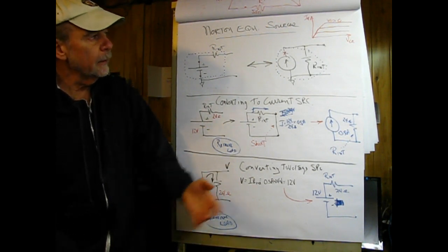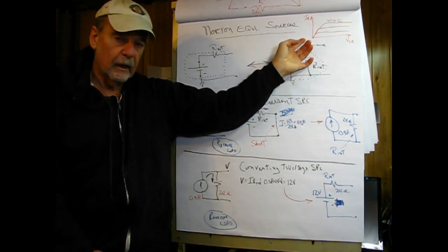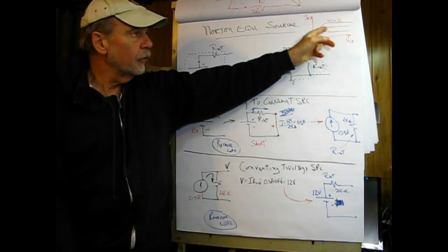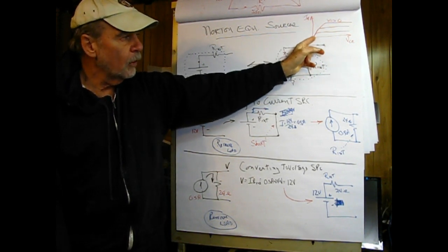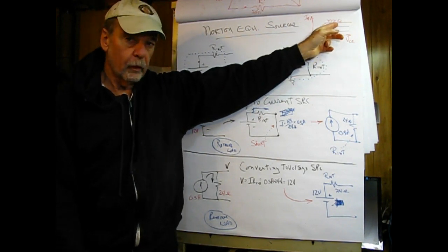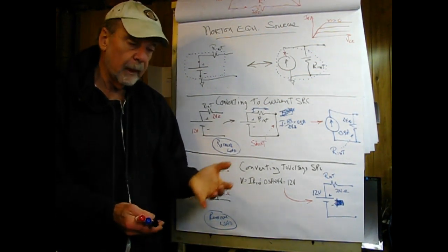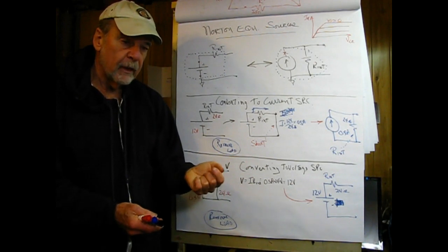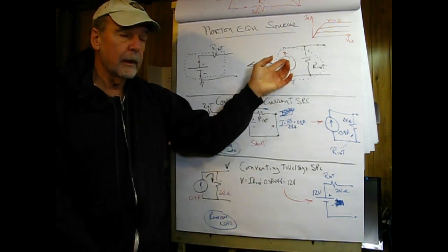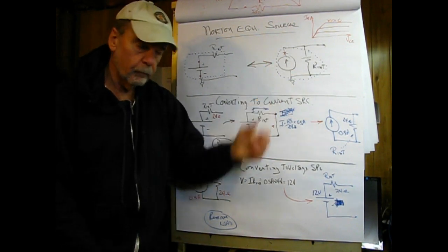Now, speaking about modeling, here we have the diagram of the collector characteristics of a transistor. Though it's well out of our topic area right now, this stands for the voltage from the collector to emitter, and this stands for the current in the collector. What I want you to pay attention to is the flatness of these curves. So as the slope approaches zero, this looks more and more like a current source in the model of a transistor, not only a bipolar transistor but field effect transistors, and it makes the analysis very straightforward. Although a transistor does not create current, and is truly a current sink, in the model of it we just call it a current source.